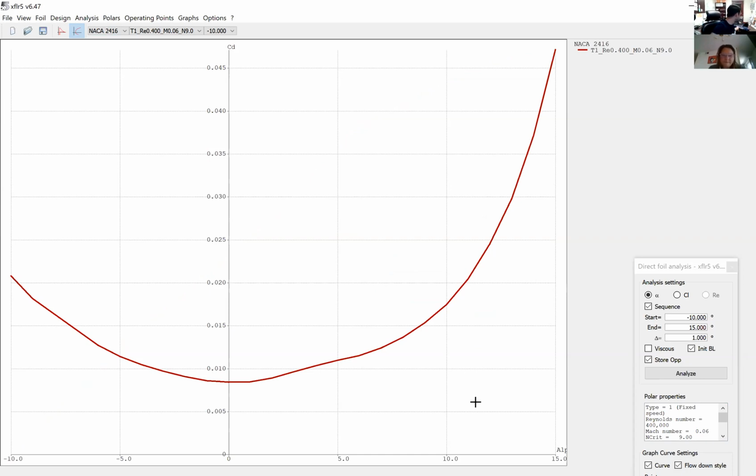If you remember, when we were discussing, if this is an airplane going with a 0 angle of attack, you have the minimum drag. You see that is a minimum, right? But once your angle of attack is increasing, so it's moving like this, you have more pressure drag because you have more surface that is touching. It's exactly like when you are in the car: if you put your hand outside horizontally, you don't feel too much drag. But if you put it like this, you will see it's forcing back, right? Yeah, you'll rip your arm off. Exactly. So this is drag.